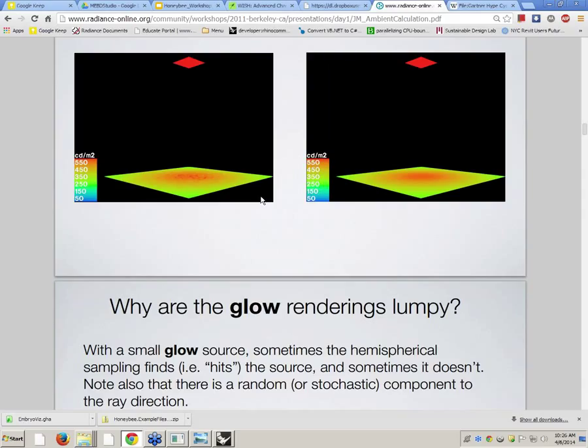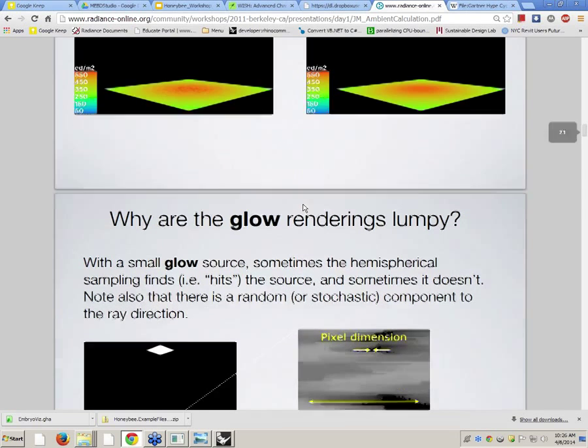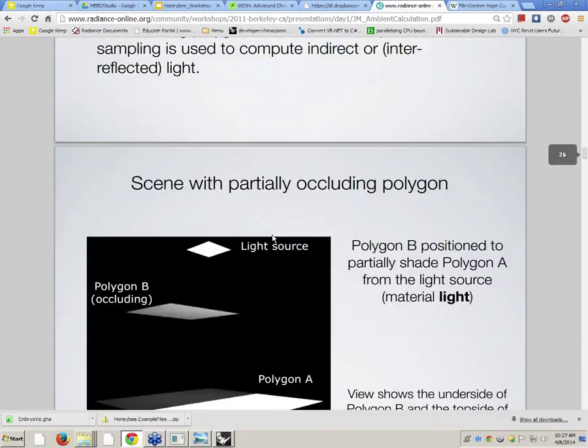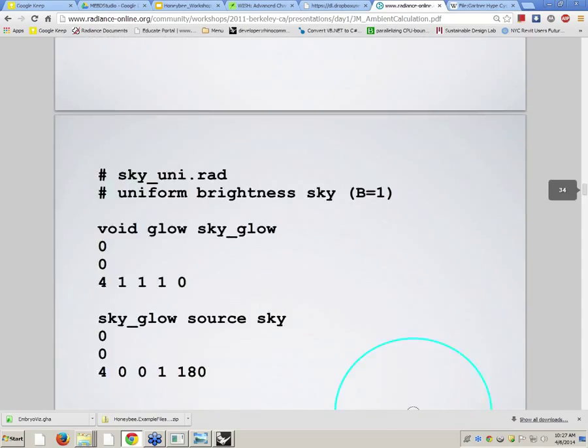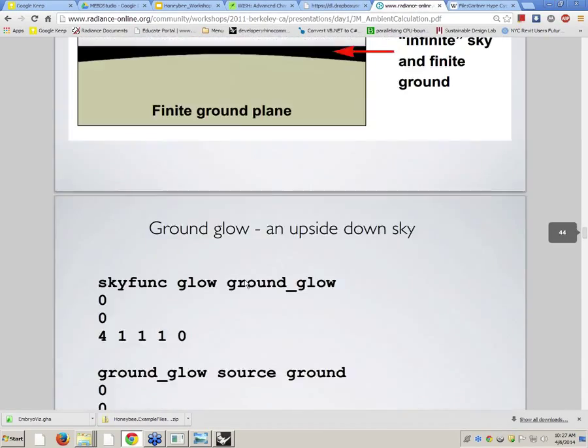And second of all, without you knowing, if you're running a grid-based analysis, I'll take care of that for you. So if you put a really low value for running a grid-based analysis, the Honeybee component will override that. It won't happen for the image-based analysis, because image-based analysis looks bad. So if you run something and it looks bad, you're not going to put it in your final presentation. But if you do a grid analysis, at the end of the day you just see some colors and say, oh, these are good colors. So I just override that for you. So you can't run a really bad simulation; you still can run wrong simulations, but not very wrong ones.